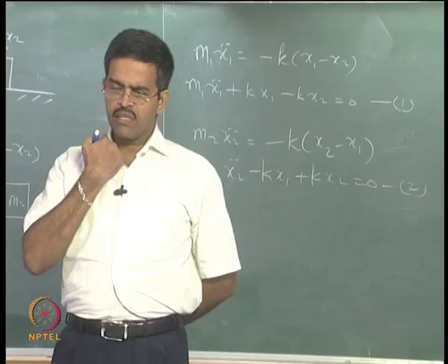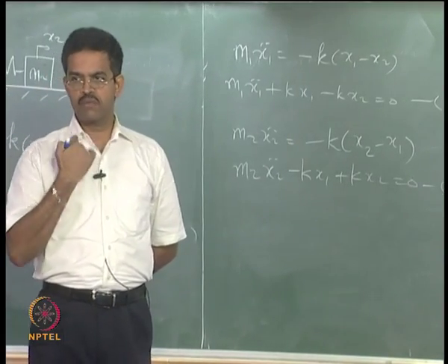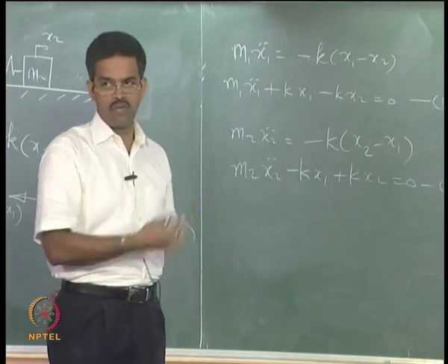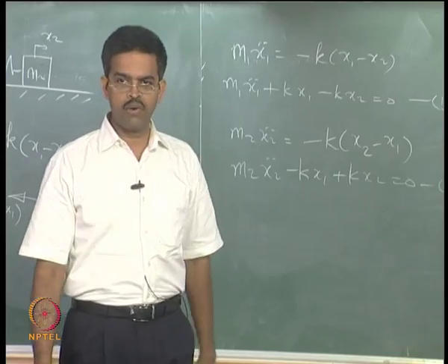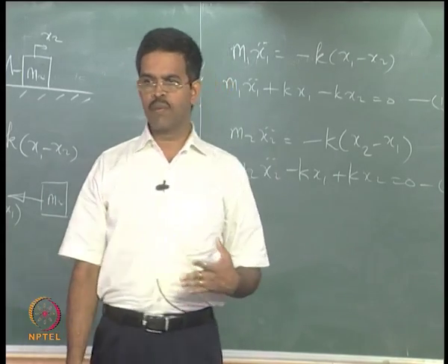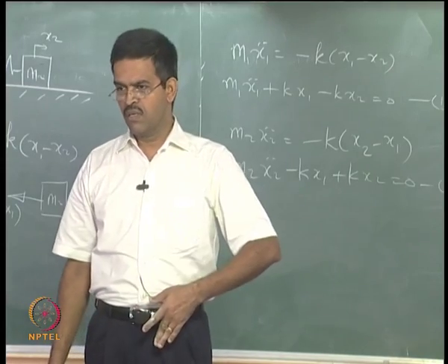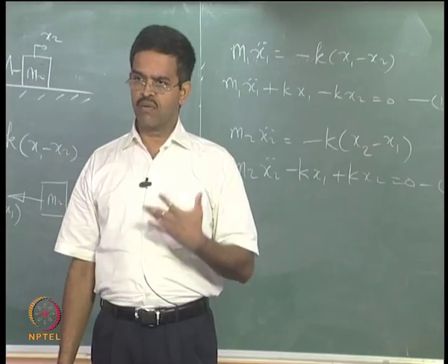But are there any cases where we do not have the lumped mass at the point where the displacements are measured? We will take an example exclusively on that form and see how to derive the mass matrix for that situation, because it is very important in our offshore structural systems. It is not necessary that the force is applied at the same point where the mass is concentrated, or that displacements are measured at the same point where the mass is concentrated.